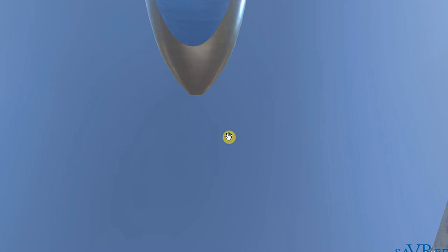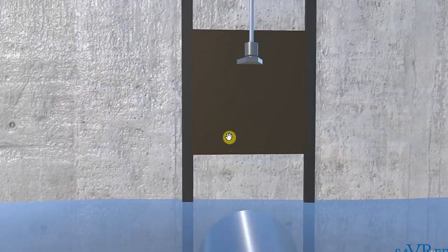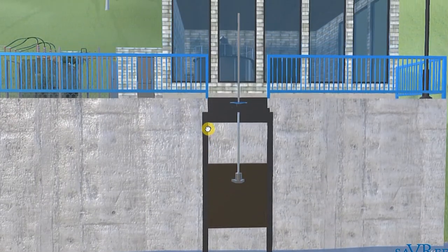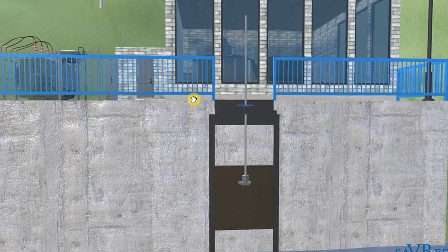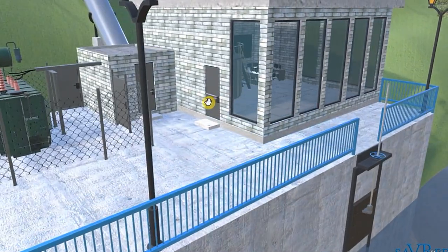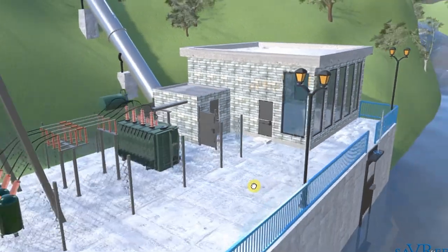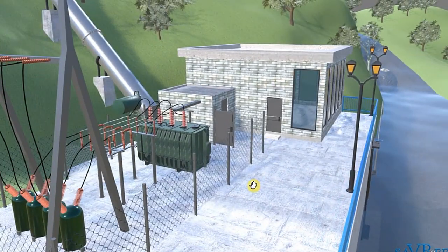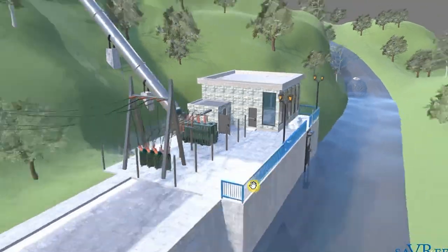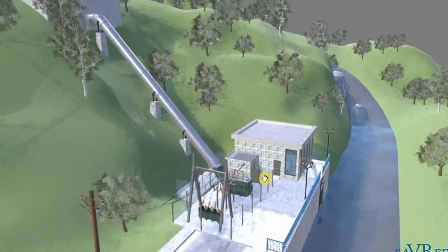If the gates or the valves are leaking, then you'll need to fix those leaks in order that you can work in the area safely. A little bit of leakage is okay, but obviously you need to be able to work in that area to perform maintenance. And it's never a good feeling if you're working in there and the space is gradually flooding. So that's the reason we have gates and valves on all of the water conductors.